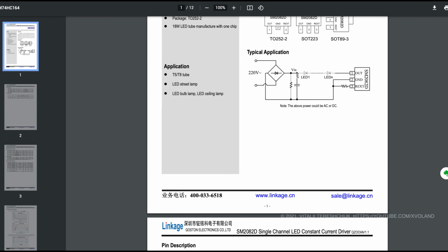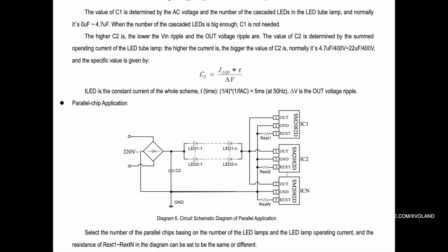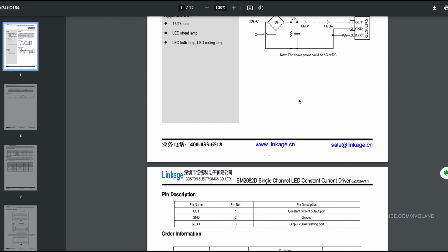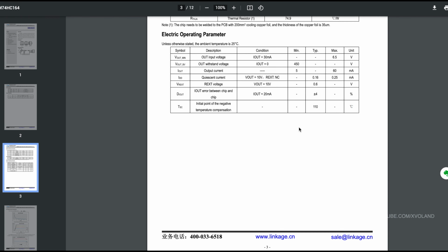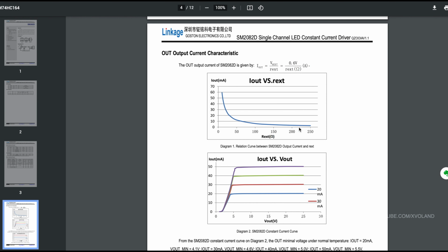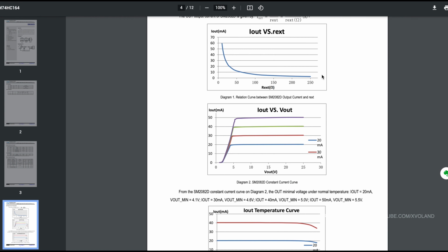My driver has a 4.7 ohm current supply resistor. Therefore, from the datasheet for another driver I could calculate the approximate values. Also, it was necessary to pay attention that they are 12 volt diodes in my lamp, because in this datasheet diodes voltage is less.